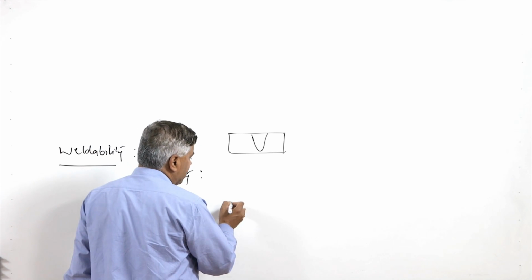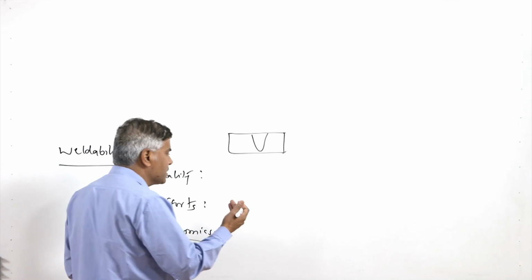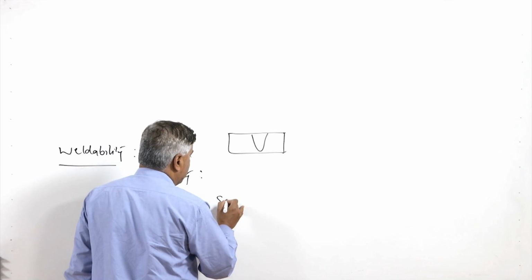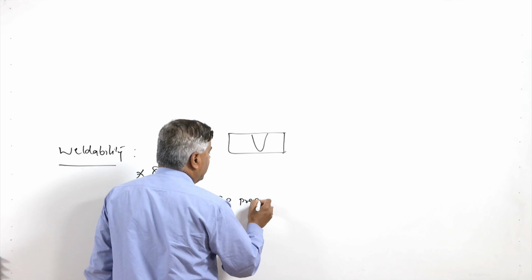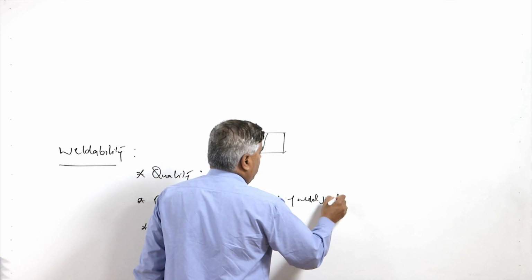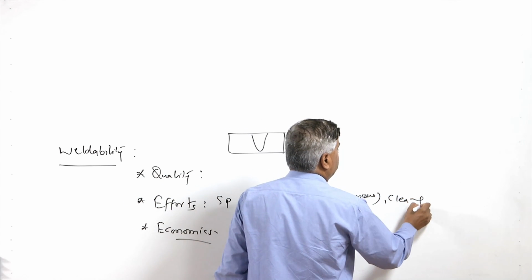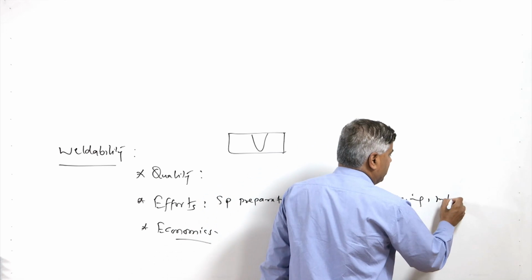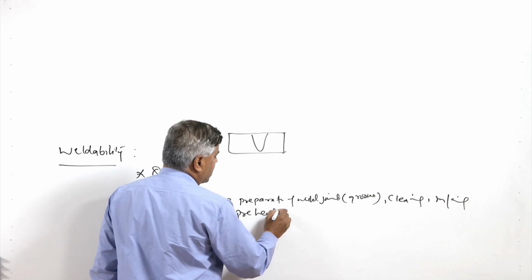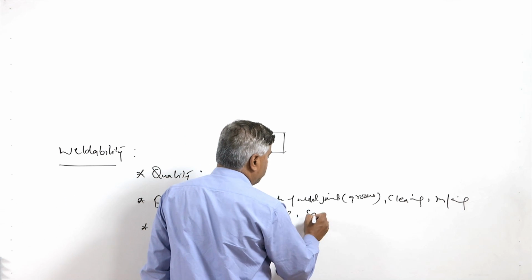Efforts are normally measured in terms of the steps we need to take to produce this weld joint during the welding, which may involve special preparation of the weld joint, maybe groove geometry, or special cleaning methods, or special machining methods, or it needs preheating of the base metal, which needs extra effort as well as difficulty.